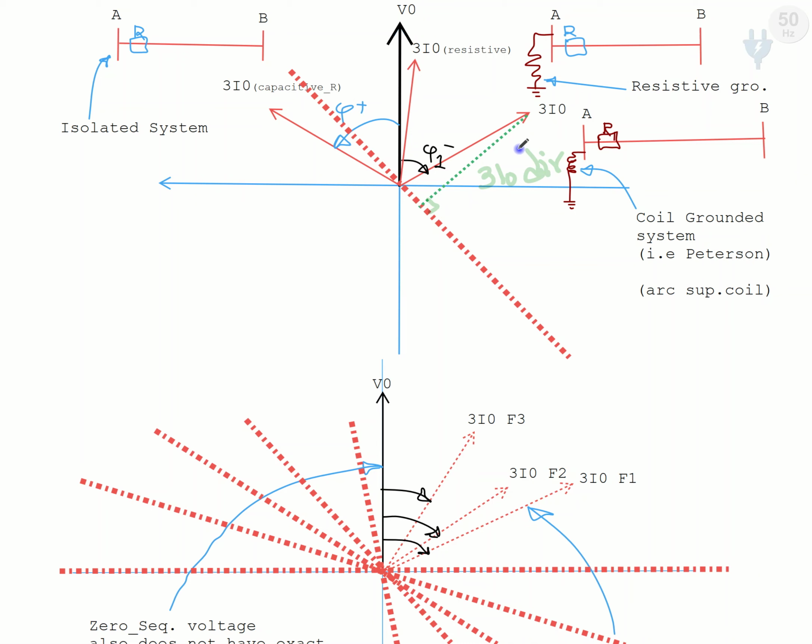For example, this is our system. We analyze that mostly the zero sequence current during the fault will be in this direction. So we take a symmetrical axis so that we take this angle from the zero axis, from the zero reference. It's a little declined because we decline it to take the majority of this zero sequence current should be diagonal.